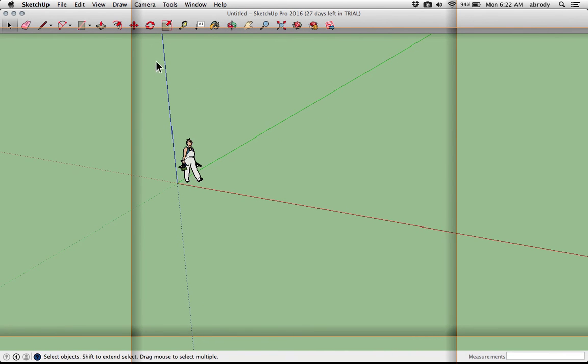Now, I'm going to draw a rectangle, and the basic tool set, the getting started tool set, is what most of you have when you install the software. And the rectangle tool, guess what? It looks just like a rectangle. And I think compared to AutoCAD, this is a pretty clean looking interface, so there's not that many tools by default. We'll add more later on. There are also some tools hidden underneath here. You see how there's a little down arrow? There's a couple of tools available, basic shapes. I'm going to click the rectangle tool. You can also use the letter R. The shortcuts that are probably familiar to you from AutoCAD are the same here.